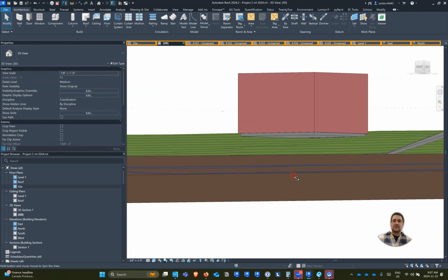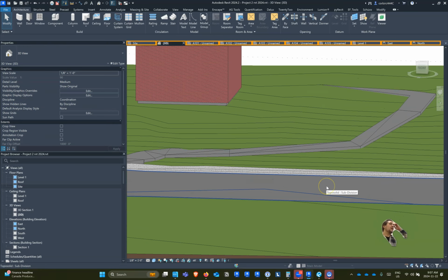And so again, we just want to make that path and follow that path with our topography, and that's kind of how you create a path. There are some ways to make it look a little bit better. I typically will try to bury it. So if we have a 12-inch slab, and that's probably what I'd recommend using, I would try to bury it so maybe only 2 or 3 inches are sticking out.